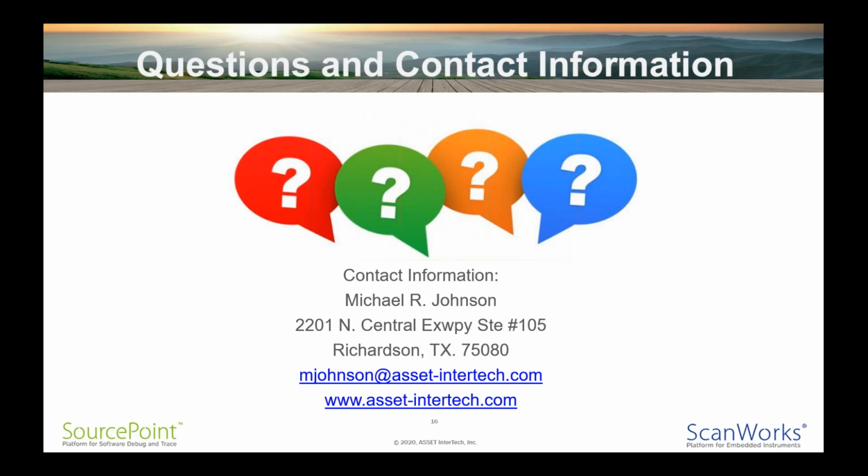I would say yes, they are. They are considered more stressful because a walking one pattern, as I mentioned in the presentation, may need to be complemented or paired with the walking zeros pattern just to make sure that you're getting complete coverage for opens, shorts, stuck-ats, and bridging faults. The Wagner patterns use a binary count pattern that is extended.